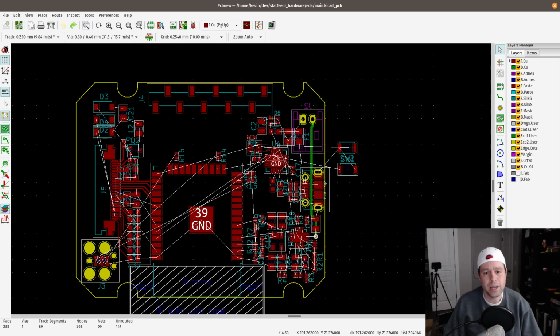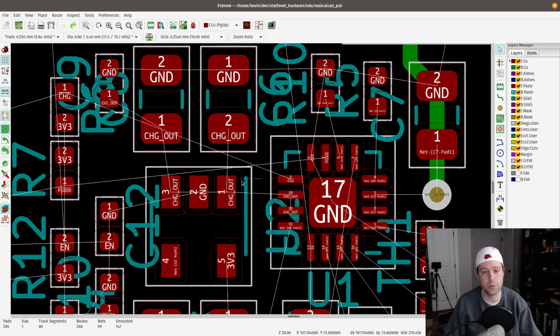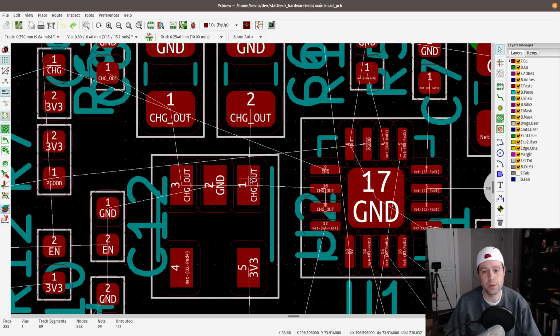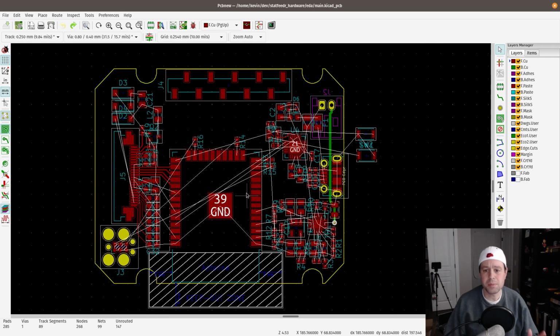And so not only are you trying to place everything to satisfy these rat's nests, like, as an example I've talked about before, this pin has to connect to this part of this capacitor. So placing them right next to each other, all we have to do is draw a little trace there, and you'll see that here in a minute as we get into this. But you're trying to think of that, but sometimes that doesn't always work. And so you have to think, how could I run something underneath? And then you have to worry about running long traces and crossing them over.